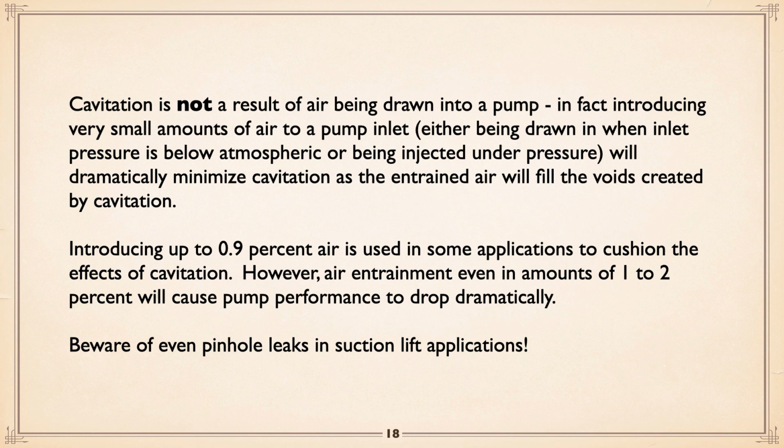However, air entrainment, even in amounts of 1 to 2%, can cause the pump performance to drop dramatically. If you've got a pump that's got a suction lift, for example, and with the pump not running, you can see water leaking out, a pinhole leak, just say drop, drop. When the pump is running, that can let in enough air in a lot of cases that the pump simply quits pumping. So suction lifts are very rough. You've got to be so careful that there is no leak of air whatsoever.